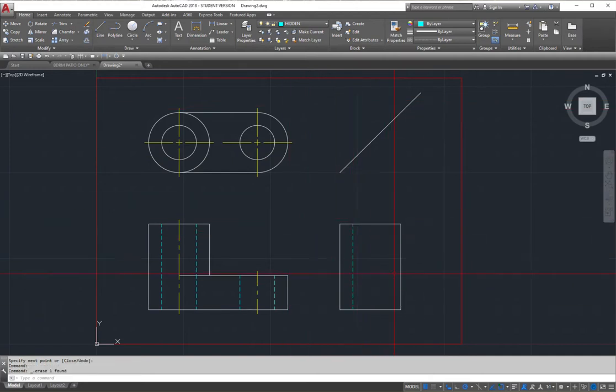I could do anything, because I know that they're equal distance, the same distance here and there. So I could mirror this line if I wanted to practice other modify commands right here. I can simply go and create that other line right here. So whichever works better for me. If I decide to mirror, I select my mirror command right here, select my object, I get my midpoint, and then I mirror that, and then hit enter.